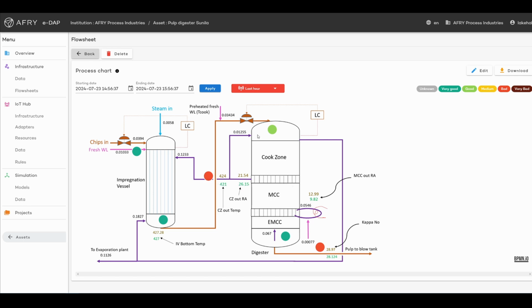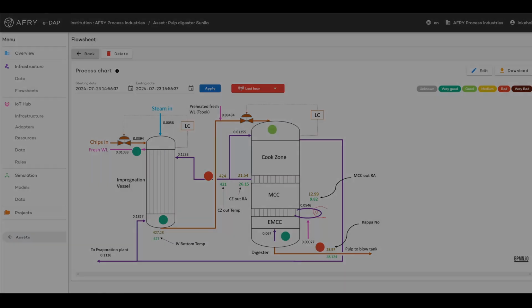The data is collected everywhere from sensors located at specific places. Important to know in this process that inside the digester itself, a production of the pulp along with other residues happens based on different conditions. The quality of the separation process and time, which normally takes between 3 to 6 hours, is usually quantified by a specific KPI known in the field as the blow kappa number.